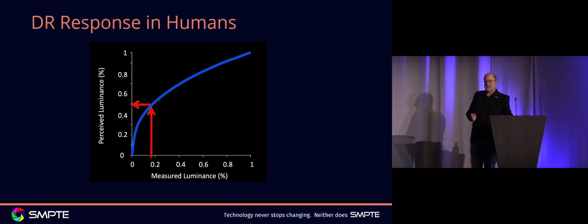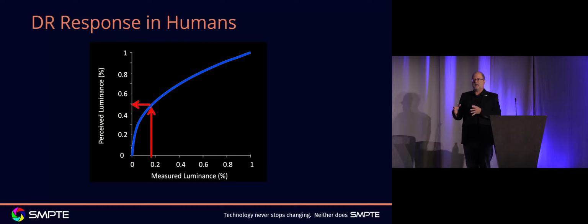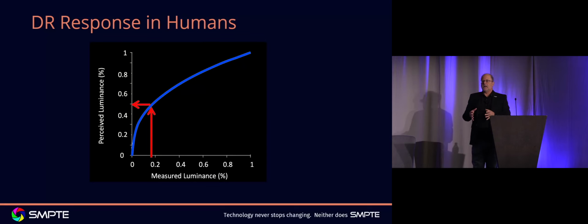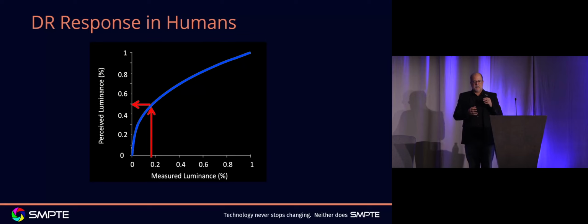Dolby Vision is kind of like HDR10 Plus in the sense that it has dynamic metadata. It also uses the PQ or ST2084 transfer function. In theatrical, it is 12-bit. In the home, it is 10-bit.